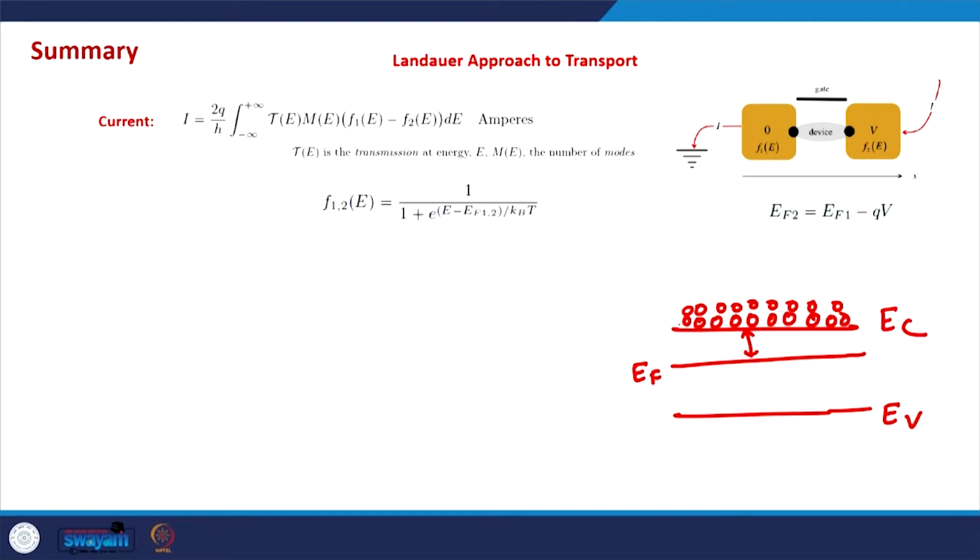And the energy of electrons, which is just above the bottom of the conduction band, is larger than EF, and it is quite significantly larger than EF, or it is many kT times. What we can write is E is EF plus kT times C, where C is a good number. C is maybe 9, 10 or maybe more than that. So, in that case, this Fermi-Dirac distribution function,